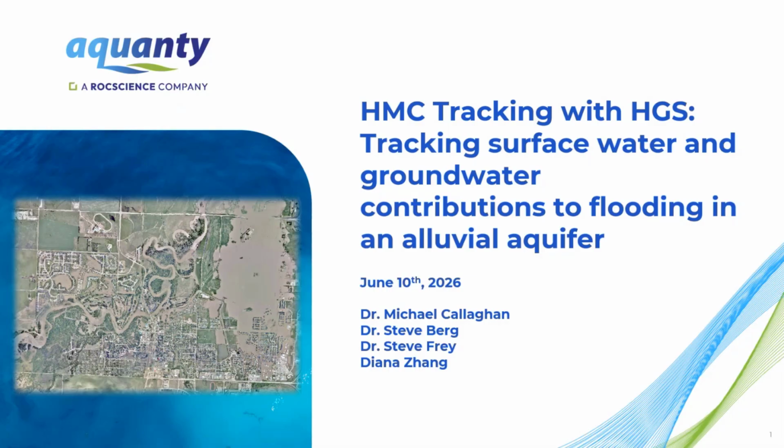The HMC method tracks the fraction of different water sources in space and time, providing a quantitative measure of those sources at any point downstream. The way that this works is we basically treat every nodal control volume in the HydroGeoSphere model as an idealized mixing cell. The utility of the HMC approach has been demonstrated in the literature for tracking hyporheic exchange in alluvial channels, calculating groundwater contributions to streamflow, and identifying sources of streamflow.